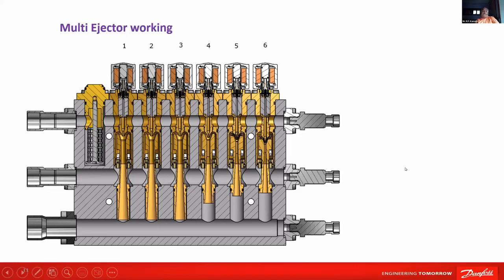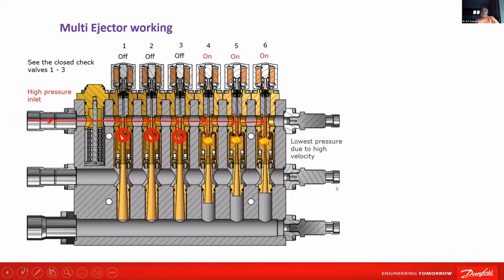How the gas flows? High pressure inlet. Now this being off, these valves are closed. That also has an additional check valve to prevent backflow. And the gas goes through this downwards and sucks vapor. Now it goes up through these nozzles outside, meaning from outside it goes in like the jacket. It goes inside and comes down, and it is delivered to the intermediate side. This is how we are managing the flow.